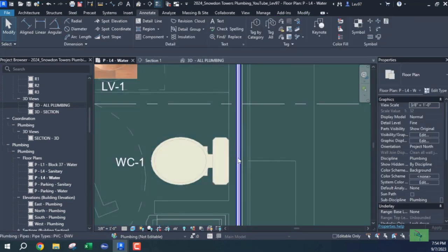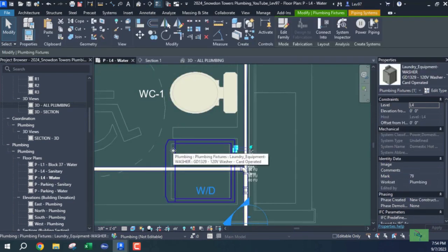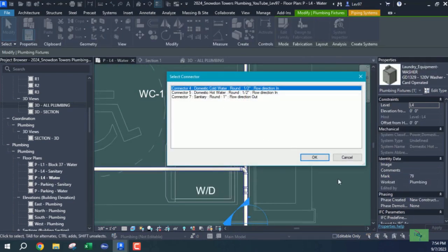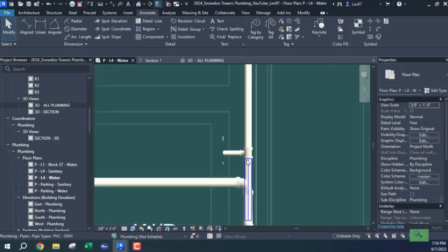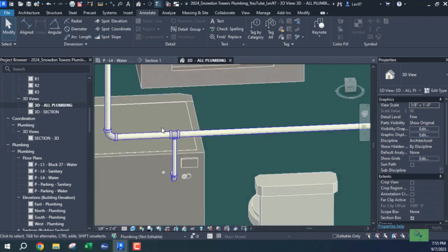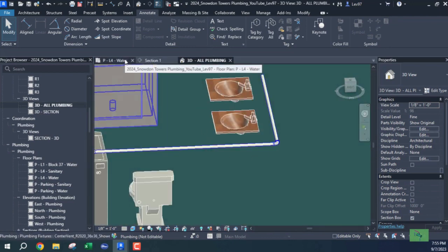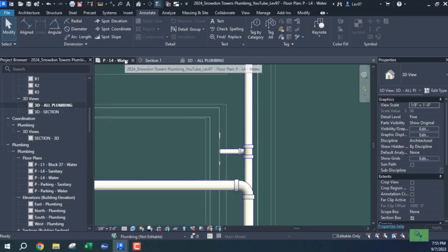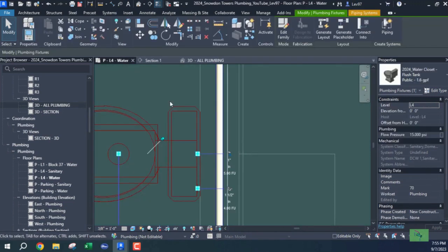There might be a few other tricks that you can use so that Revit doesn't make that loop, where you choose your fixture and you want to connect into a pipe, whatever system that is, and you choose your pipe system. Let's go back around, and that's the connection you want. You don't want it to loop all the way out to the end, which it has a tendency to do. So just be careful when you're doing that, because it's not going to work all the time, but just keep trying it. It may or may not work.